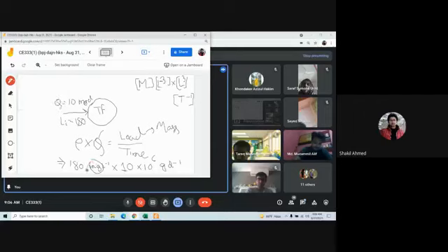So here milligram is the mass. Then liter is volume, so we have put L to the power minus 3. Then gallon is L cubed volume and D is the time. So here it cancels out, and what remains is mass per unit time. So if you multiply rho into Q, it becomes mass per unit time.